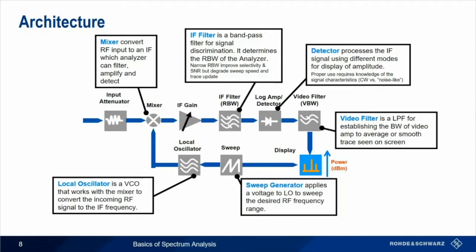So as long as you aren't capturing a very, very wide frequency range of interest, you can have very fast sweep time. You can do things like real-time operation after the IF filter using an FFT. Spectrum analyzers get you very high SFDR, spurious-free dynamic range. So a lot of nice features of the spectrum analyzer.